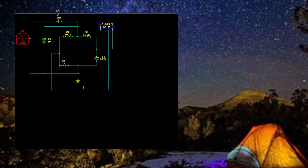The magnitude again is 1 millivolt. Now we can do the analysis setup, do the AC, and then we're going to run from 100 hertz. Okay, let's see if it works.